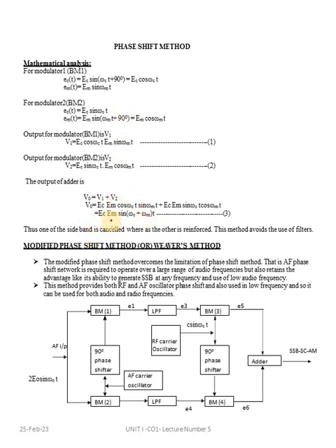So E_c E_m sin (omega_c plus omega_m) t. The negative sideband gets cancelled. One of the sidebands is cancelled, whereas the other is reinforced. This method avoids the use of filters. So the balanced modulator and the phase shift itself avoid the unwanted sideband frequency.